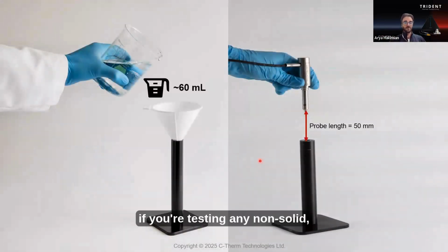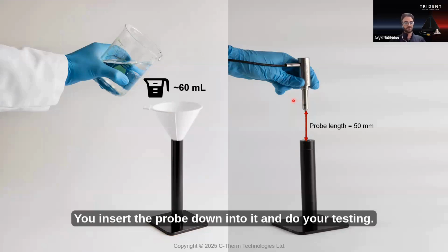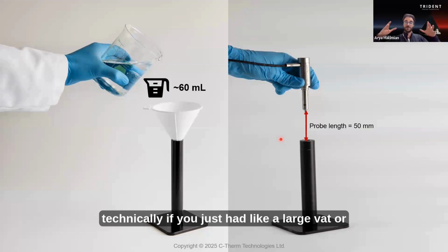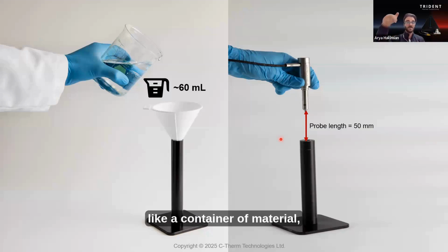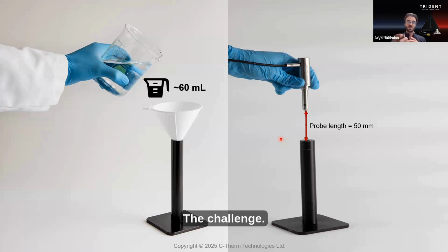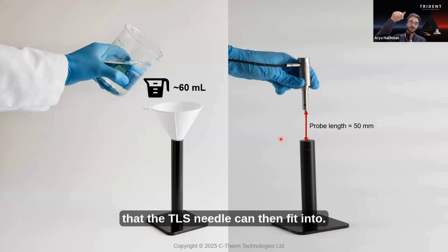Now, if you're testing any non-solid, there is a standard cell that typically is provided. You would fill that up. It holds about 60 milliliters. You insert the probe down into it and do your testing. Alternatively, technically, if you just had a large vat or container of material, you could just stick the probe down into that. You can use the TLS for testing solid samples. The consideration would be you're going to have to drill into it, because you're going to have basically a slot or a hole that the TLS needle can then fit into.